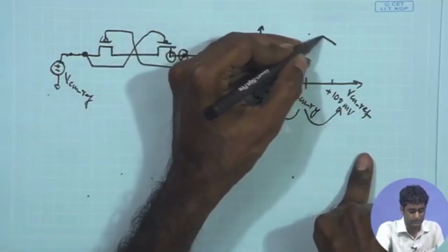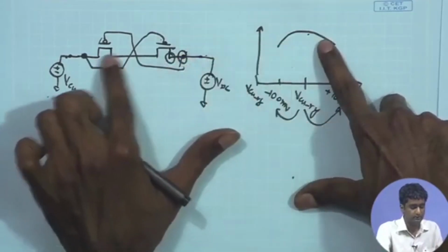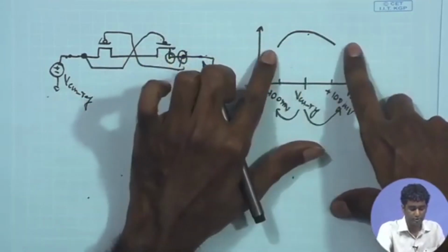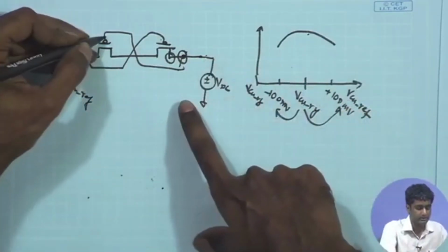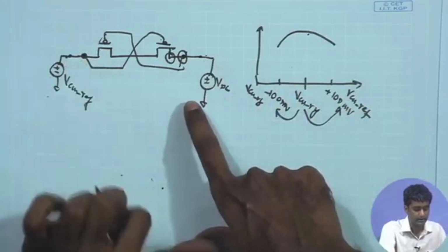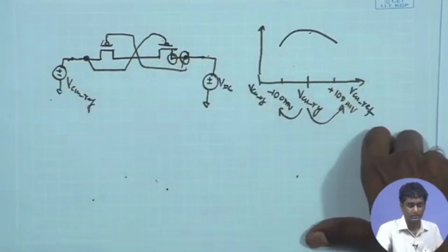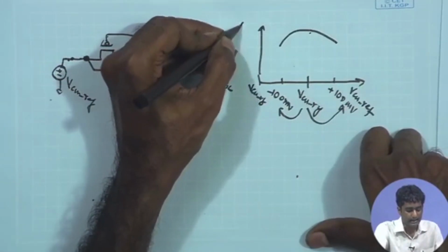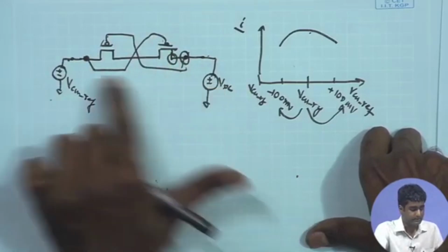So, the impedance characteristics may look like something like this. For smaller differences, it gives you a high impedance, but as the potential difference increases because of increasing leakage components, say the leakage component between gate and bulk and the gate and the junctions, it will lead to reducing impedance. So, that is what we expect if you plot the I divided by delta V, that is the V DC minus V ref.